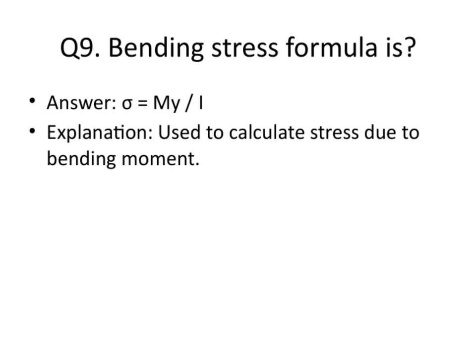Larger I means less stress for the same bending moment. So, this formula is a key tool in our structural analysis, allowing us to predict where and how much a beam will bend and stretch under load. And speaking of the formula, it's central to our understanding of bending stress, which brings us to our next question. What is the actual formula for bending stress?